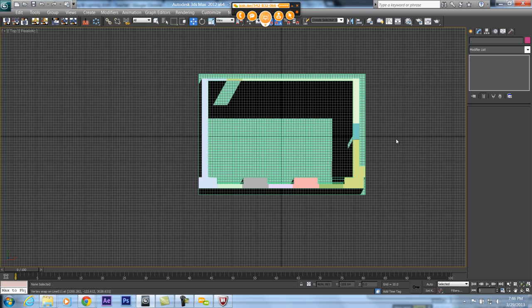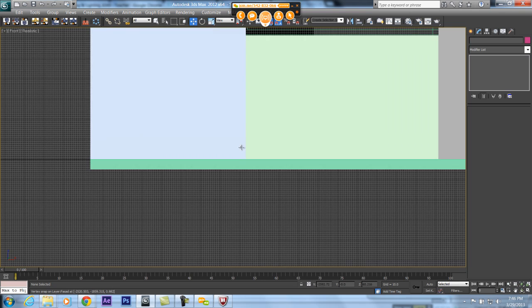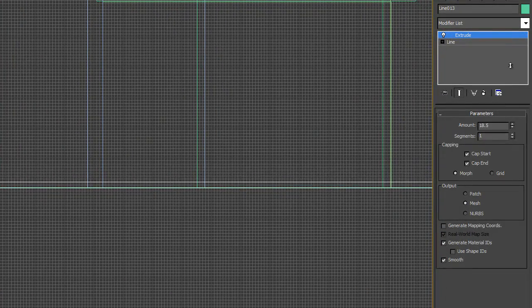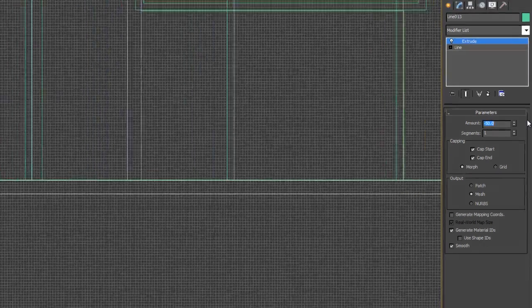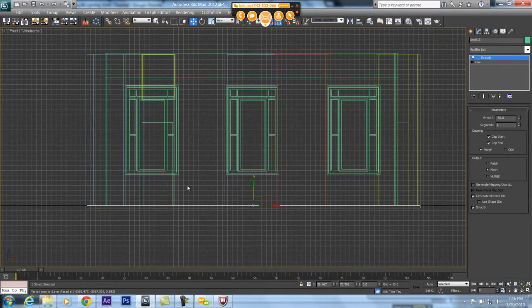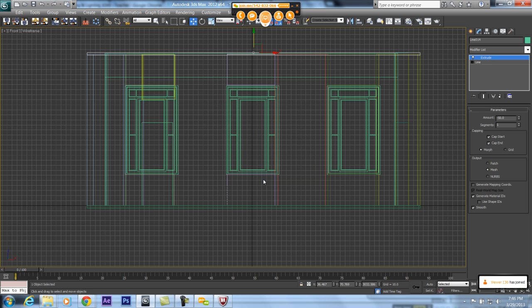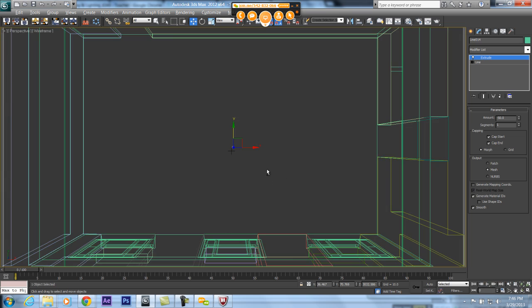And in that case, if I press F and see this from the front view, as you see here, if I go into plus, I'm going to go up. And each model that I'm going to bring is going to be in the floor. And I want to avoid that. In order to do that and not mess with your floor by moving it up and down, you just go into minus. Minus 50 will do the job. I'm going to press Shift and duplicate this and make my ceiling. Voila. Press OK. And we've got our roof.